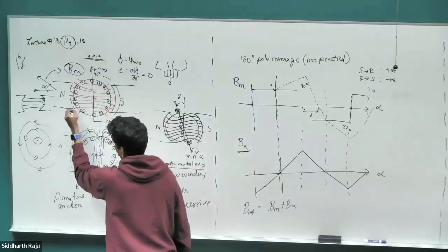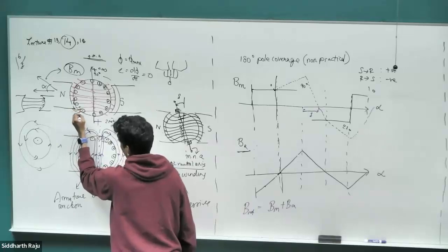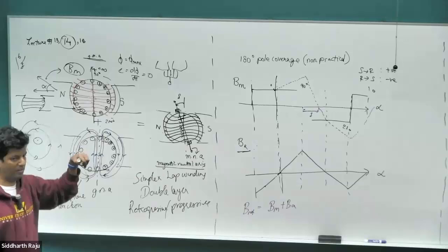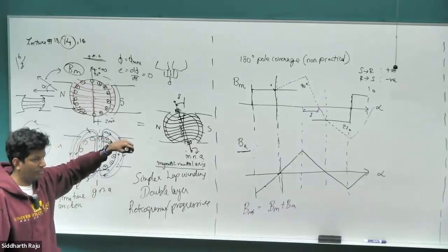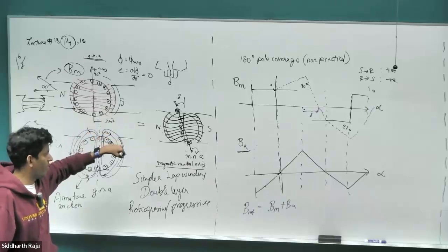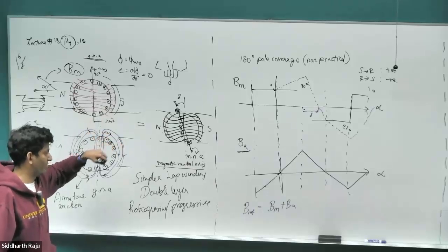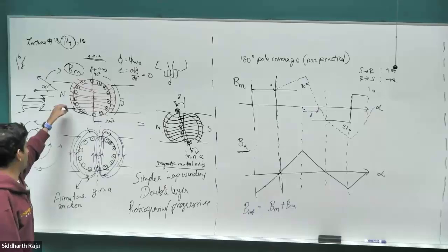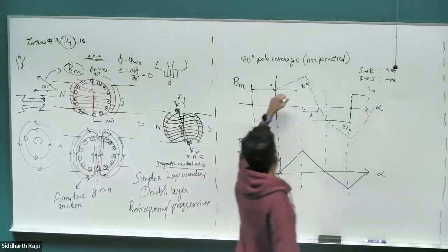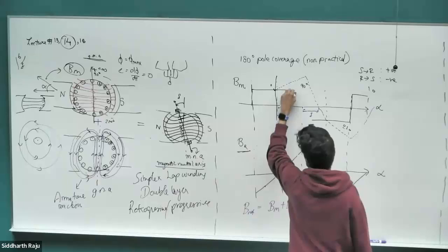So the magnetic field here takes a longer pathway. And we already saw what happens when you have a larger air gap: the load line starts to have a slope that is much lower. So where it intersects the magnet becomes much further down in the low B field, or much higher H value, negative H. So the B field here would be much, much lower and weaker.